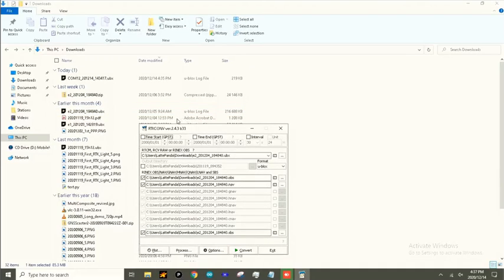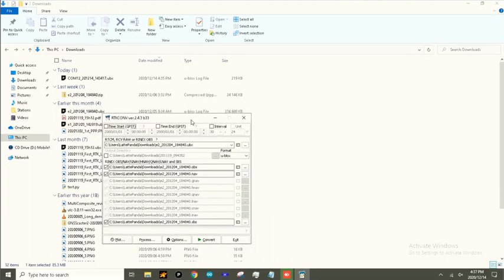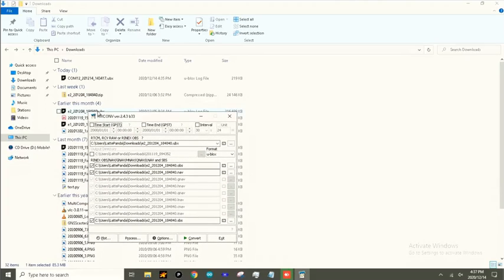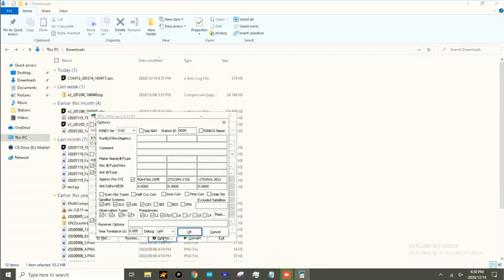And now we can regenerate that observation file from our UBX raw data collection. So once all of this is done, we can also go into the options file to ensure that all the applicable frequencies and constellations have been selected to ensure that we make the most of the data. So for this particular receiver, I've enabled L1, L2 and L5 bands, all the observation types, as well as GPS, GLONASS, Galileo and QZS.